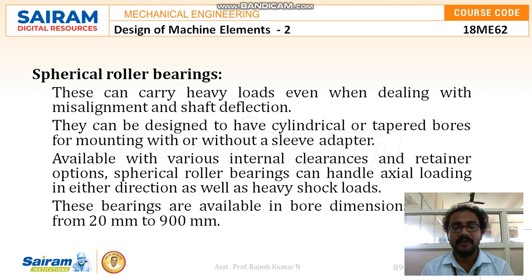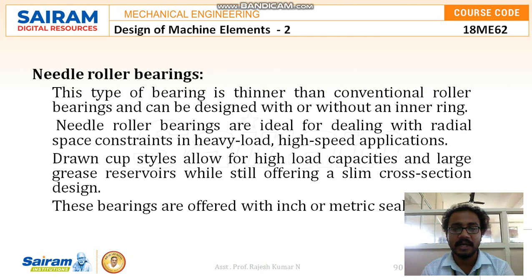These can carry heavy loads even when dealing with misalignment and shaft deflection. They can be designed to have cylindrical or tapered bores for mounting with or without a sleeve adapter, and are available with various internal clearances and retainer options. Spherical roller bearings can handle axial loading in either direction as well as heavy shock loads. These bearings are available in bore dimensions ranging from 20 mm to 900 mm.